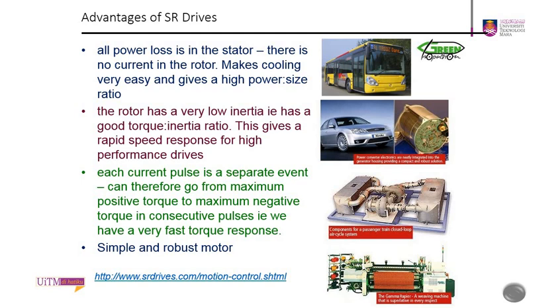Each current pulse is a separate event, so it can go from maximum positive torque to maximum negative torque with a very fast response in consecutive pulses. With fewer components in the rotor, it is simple, and thus it makes a robust motor.